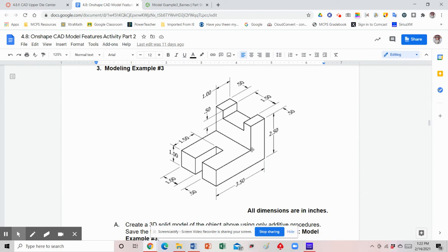But I also notice that I have a back section here, okay? So again, there's multiple options you could do. You could extrude it all the way up 2.5 and then cut away a larger rectangle, or we could do this in stages and go up 1 and then add a rectangle to the back. Completely up to you how you want to do it, but that's the way I'm going to do it. I'm just going to extrude it up 1 inch and then add a rectangle to the top to finish off this back section here. So I'm going to go back to my figure.